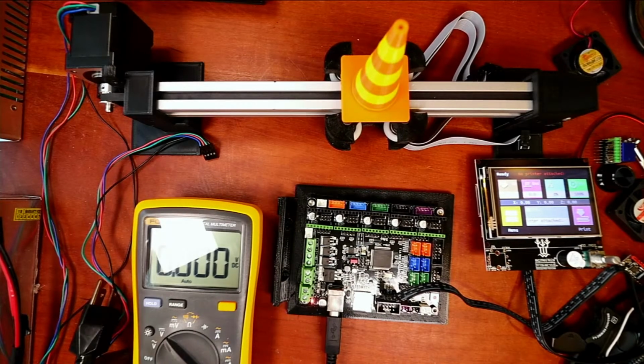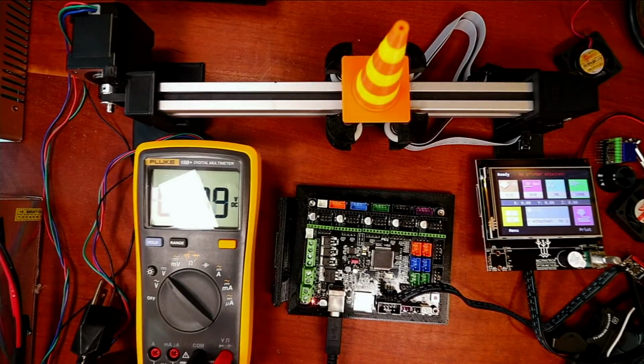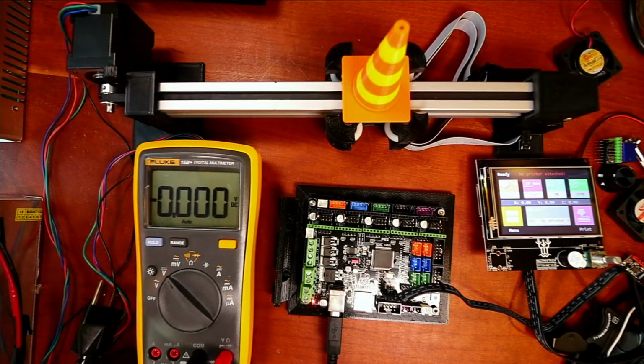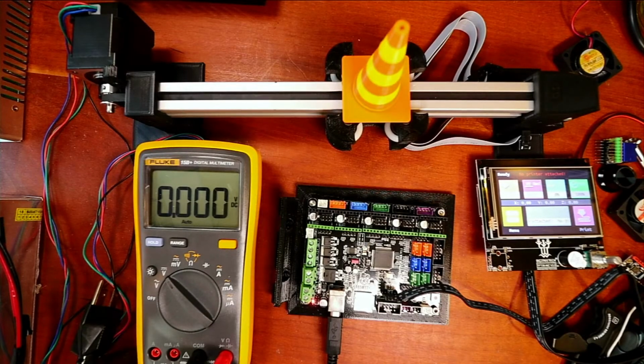I know there's a reflection on this when I'm using it. I can actually turn that light off for the moment. But essentially what I did is I measured the pins on the board and realized which pin was actually hot, with the most voltage being 4.28 volts or something. And that was the one that we needed to connect to. So without having the directions, you can actually decipher what they're talking about to a degree instead of using their browser.